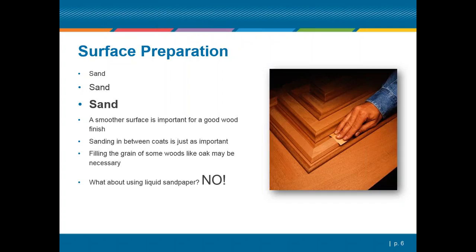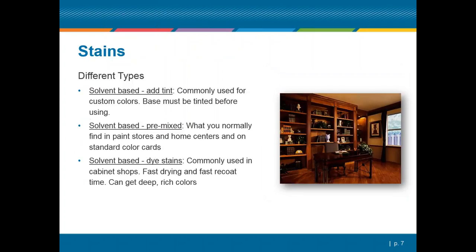And that may require going through several different grades or grits of sandpaper to get to that surface level. But that is dependent upon the individual, and upon your design criteria as to how smooth that finish is and what kind of finish we get to. So again, application is a huge issue here, and surface preparation is the beginning point as it is with virtually any kind of paint finish, but specifically with wood finishes here, it's extremely important.